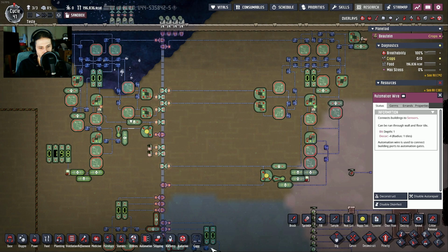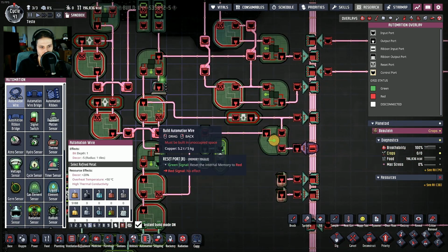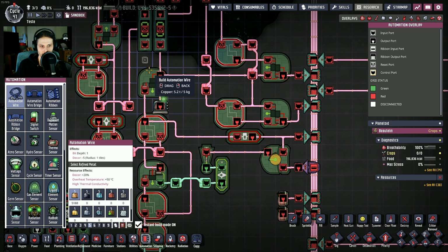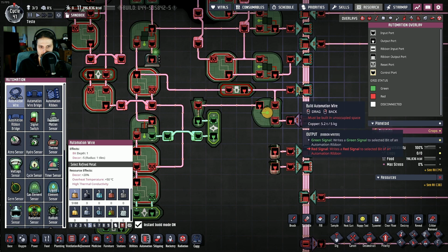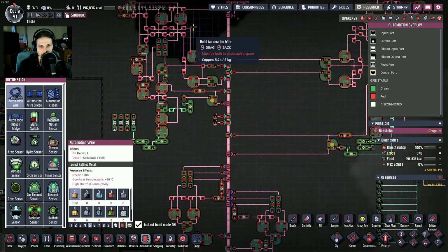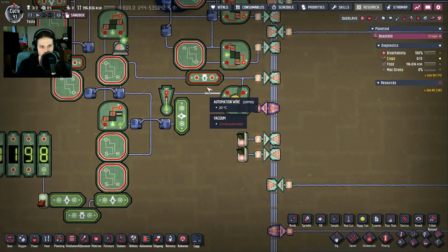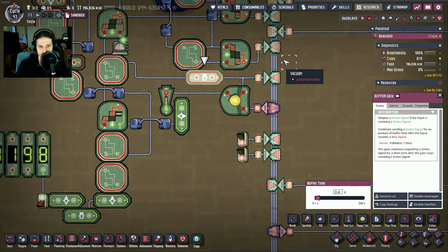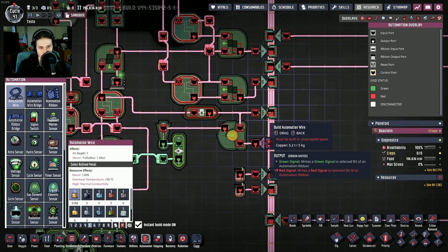So pretty much what you need to do is quite simple. As we established before, this memory toggle over here, the one that turns on and off the frequency generator, sends a signal into bit 3. So what you do is you have this wire that goes into bit 3, you put a buffer gate because the system becomes deactivated before the confirmation of ping 4. So you need this buffer gate over here with a little bit of time just to make sure that nothing is written before the ping 4 is received. That's why it's here, and in here it writes into bit 3.